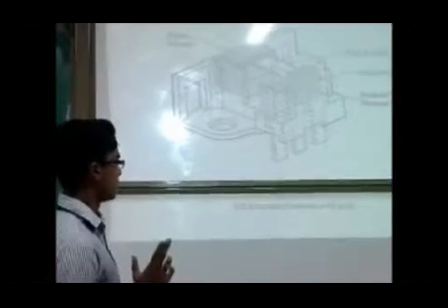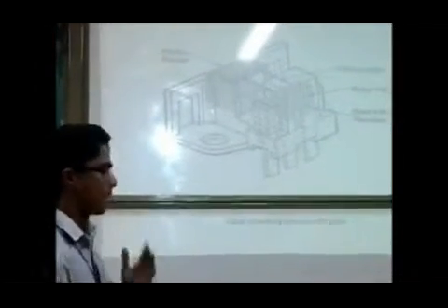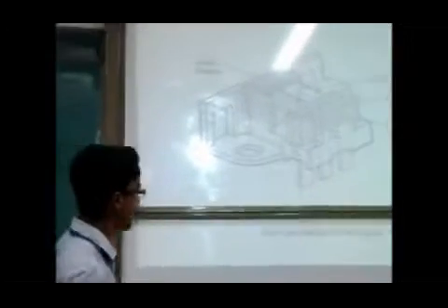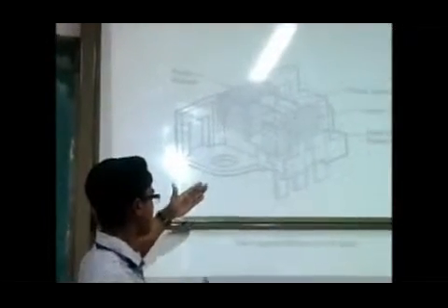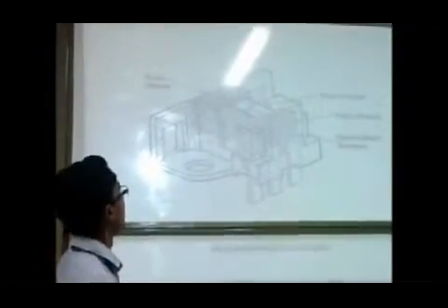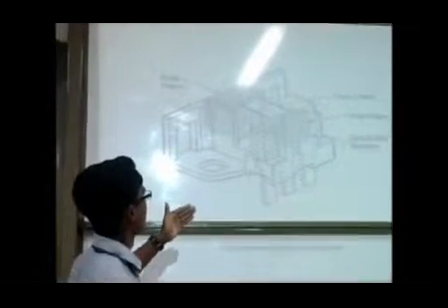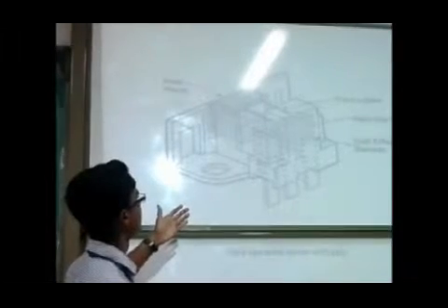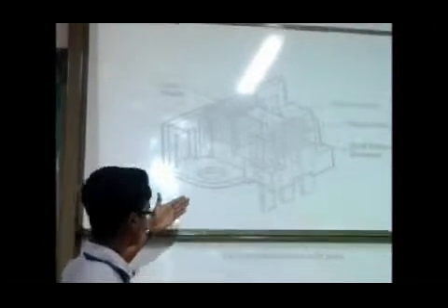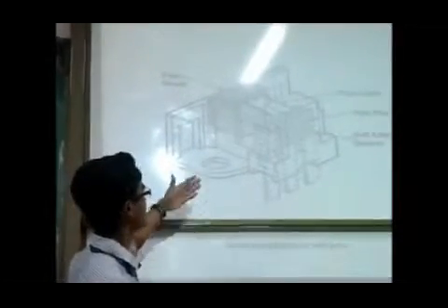Whenever a vane is passed through this gap, it will cut the magnetic field lines in such a manner that the sensor will be turned off. Like that, we can find out whether the vane is present in this gap.